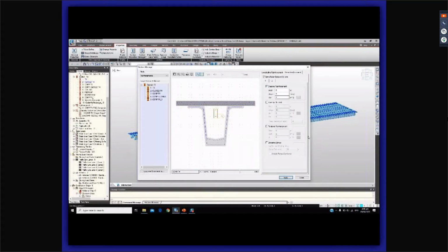Then let's do the same for the shear reinforcement. Let's input diagonal reinforcement. For diagonal reinforcement, let's input pitch as 150 mm or 0.150 m, then angle 90. Then input the number of reinforcement for every meter. And for torsional effects, let's input the same data. If you have a preliminary design for this, you can also do that. But this is optional. You can just check your model first, get the recommended area of steel, and then input it afterward.